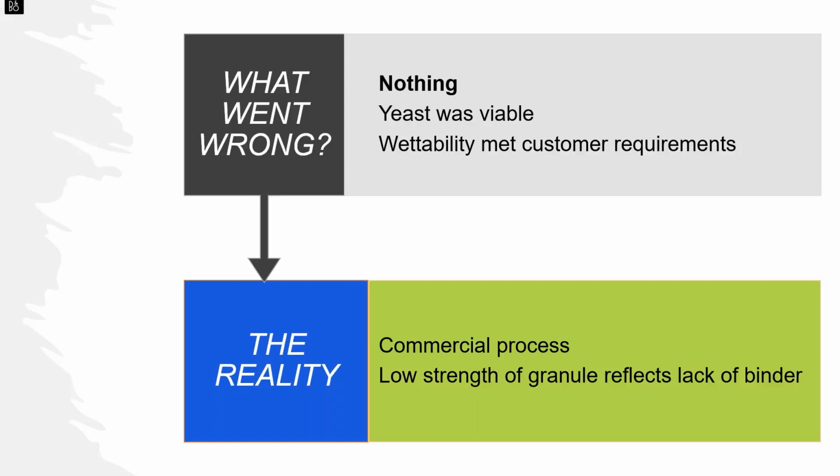Now, it was okay with the customer, and so it was okay with me, but it was a very good learning experience: you can do something right, and subsequent steps, in this case drying, can have a really big deleterious effect. I want to point out that this is one of the big issues in drying and granulation, particularly in fluid beds. You don't want to over-fluidize, because that will cause your particles to break up, and you do want to have some sort of binder in there to help stabilize the whole system together.